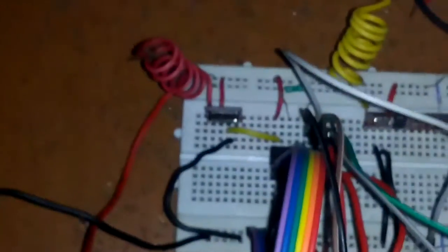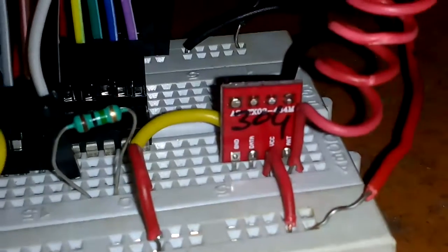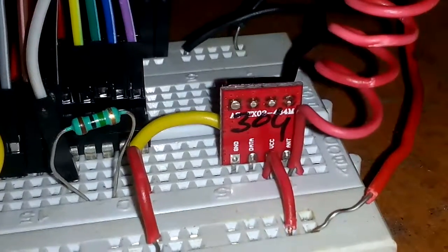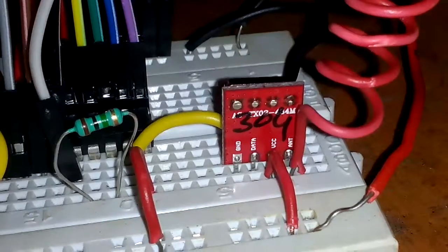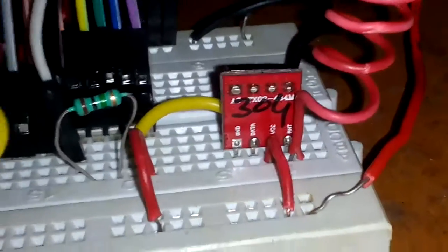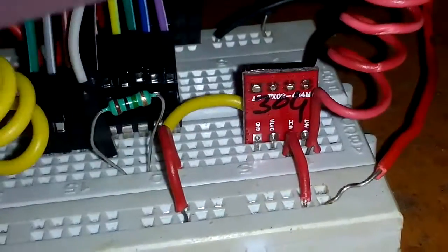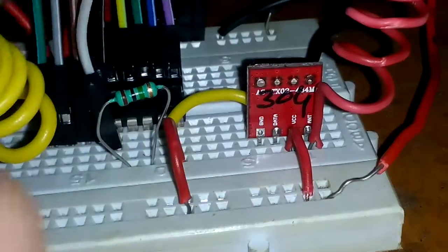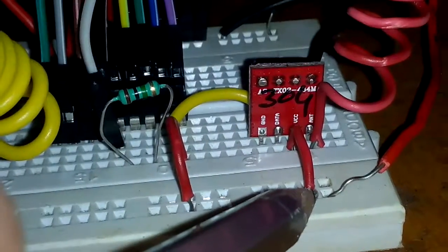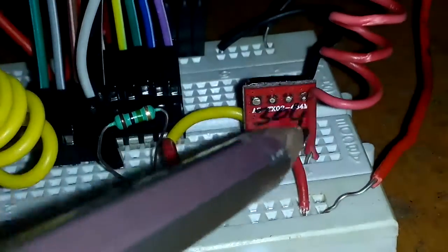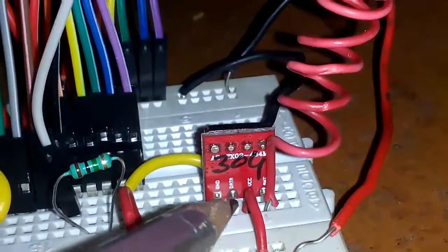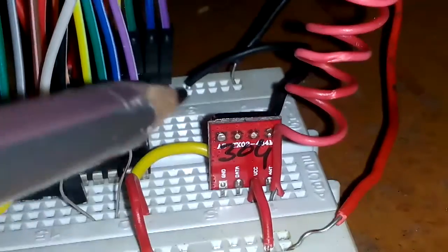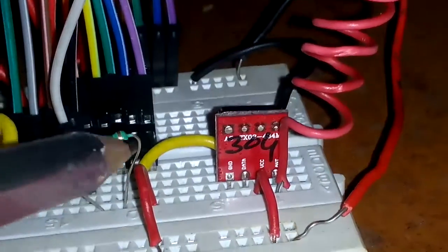I can show you that the RF transmitter requires power, ground, and so on, which is already given behind this model of an RF transmitter: ground, data, VCC, etc. So now you can easily give the supply and ground from the other side. This red wire indicates that we are giving a supply of 5 volts, and this one is for the antenna. Data comes from here for transmitting, from the HT12E encoder IC.